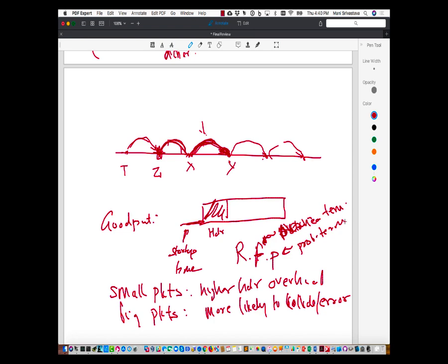Is it because of the electronics that the receiver power goes up, for short range radios? Well, obviously electronics consume power, right? And at the same time, if you're really short distance, radios are operating at a milliwatt or some milliwatts of transmit power. So electronics just begins to dominate at that stage.